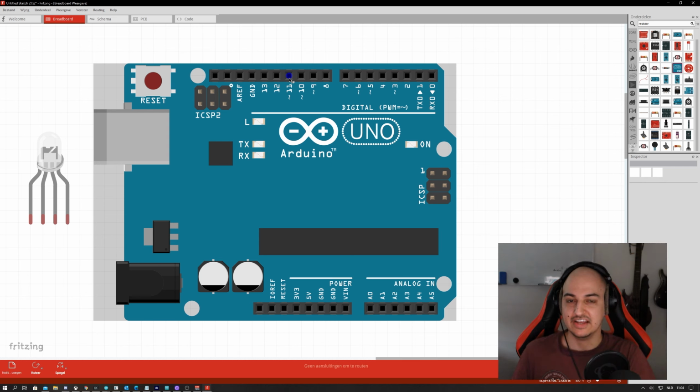In code, we can actually see, if we would measure this, that it would just be an on or off signal going towards our LED. So even though it's analogWrite, it's not really analog. And even though we say it runs not as bright, it kind of doesn't. So that can be confusing when you encounter this. And even for me, I thought that the analogWrite could be used on the A5, A0, and A1 as well, but it just isn't the case.